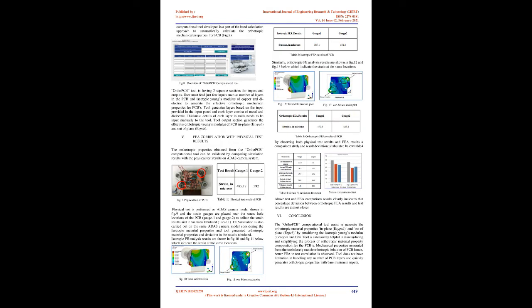The copper is measured in ounces. PCB manufacturers will refer to the copper thickness in ounces, but during board layup, or when the materials are stacked together, the inch/mm thickness is used.